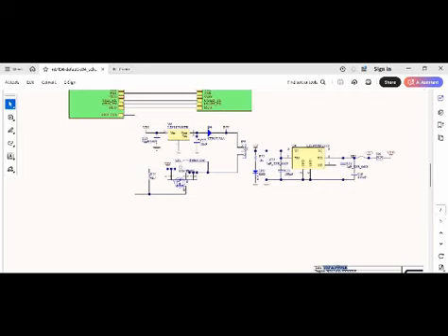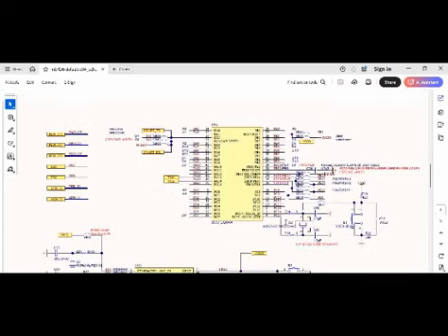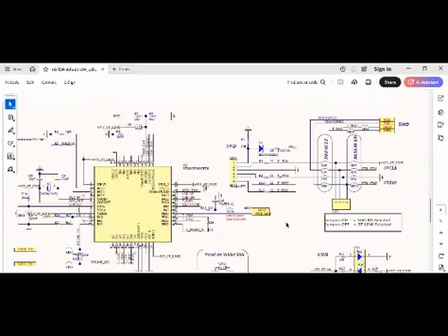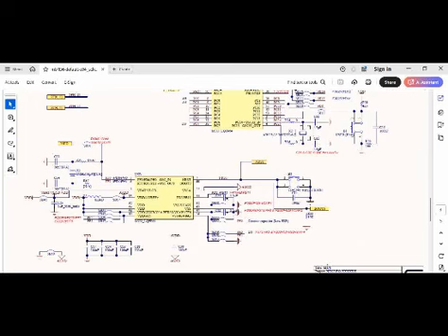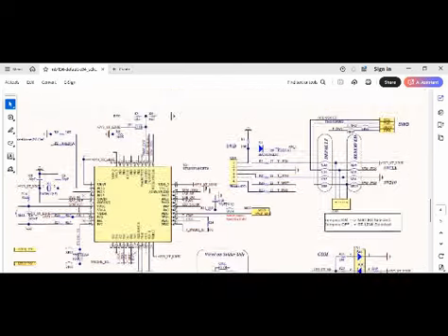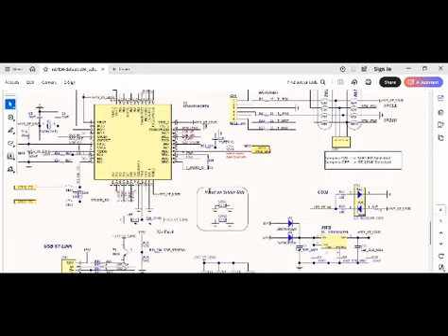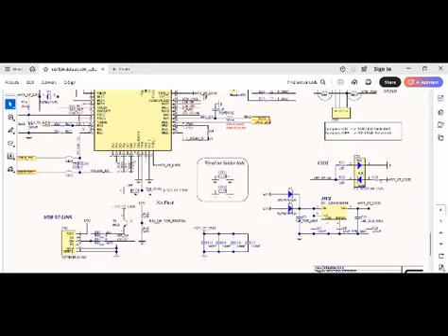So if you are new to the schematic, you can actually understand the sections by seeing the title page here. You can see here, this is the top section and power, and this is the MCU section. This is for pretty much beginners, and you can see here title ST-Link. So if you don't understand the schematic and you are coming here for the first time, this is the way you have to at least first start and then go further in depth into each and every section. So this is the ST-Link section.